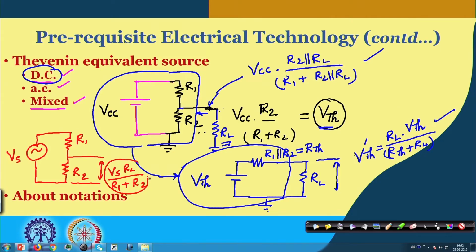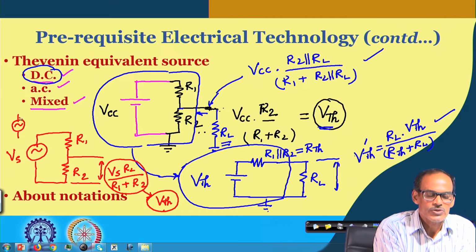Now, in this situation, of course, you can say that this is nothing but the Thevenin equivalent voltage. So, whatever Thevenin equivalent circuit analysis you know under DC condition, here also you can do the same or a similar thing. Instead of seeing this entire circuit, the circuit can be represented by 2 elements, one of them is this V t h and, of course, the Thevenin equivalent resistance. So, now this circuit can be replaced by a Thevenin equivalent signal source in series with a Thevenin equivalent resistance.